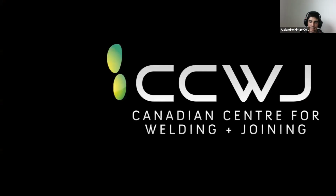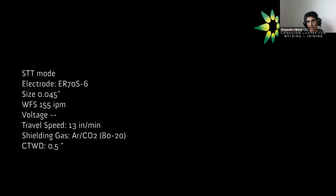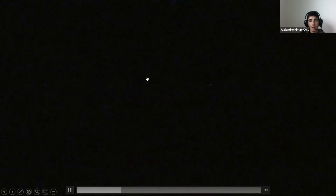This is surface tension transfer mode. This is a Lincoln specific mode, but Miller has their own, Fronius has their own systems, and it's the one that we saw that has this complex current wave, which has a background current and a peak current, and they play with that to actually detach the molten metal from the wire.